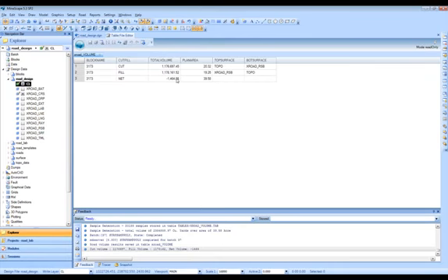And here we can see there is some difference, and that difference could be from where we're taking our cross sections, how many cross sections we're taking, and that we're taking them at the stations and at the curve areas. We may need more for our average end area volumes. We may want to have more cross sections or take more samples along that area, so might reduce our stationing, or again we could just grab these numbers, and that's a pretty reasonable cut fill balance in this particular case.